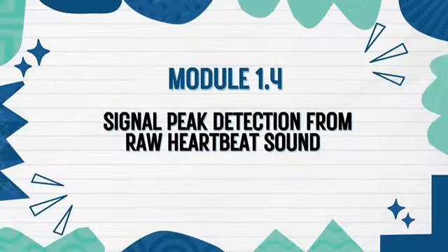Maintain the connection from previous module. Copy the coding from module 1.4. Compile the coding and upload the coding into ESP32. Press the boot button for 3 to 5 seconds.